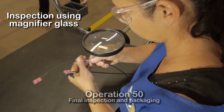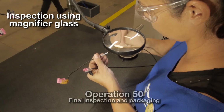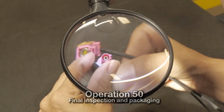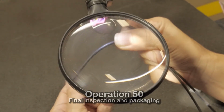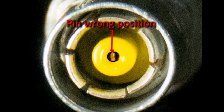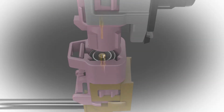Final inspection includes observing that all components are present, no damage to the product, if the ferrule is crimped, loose wire strands, position of the pin. Position of the pin is very critical to the performance of the product. Wrong position of the pin will cause assembly issues at our customers' plants and less than desired performance of the product.